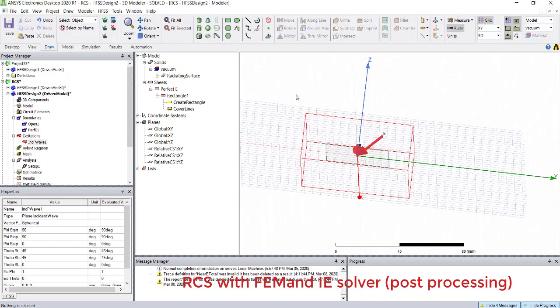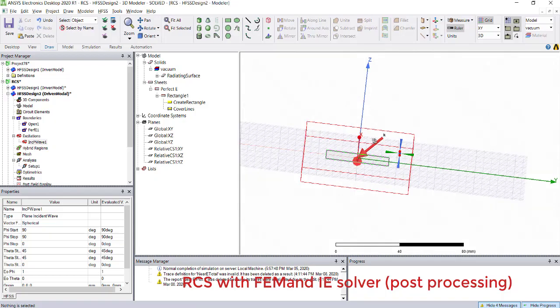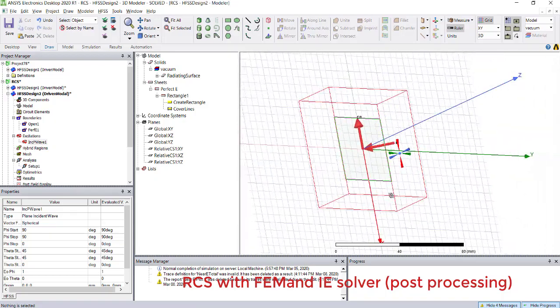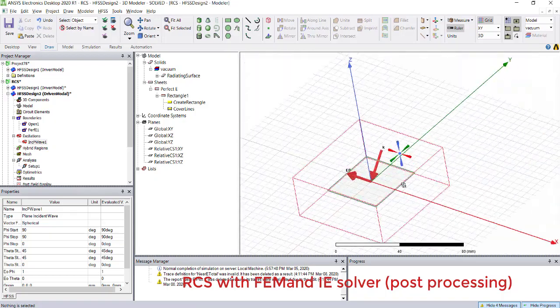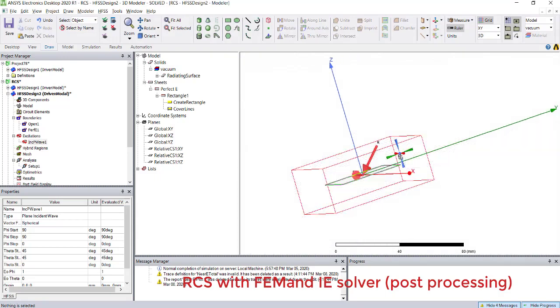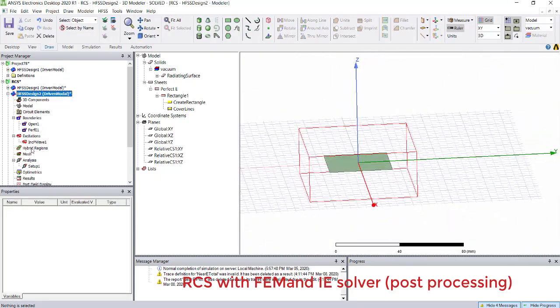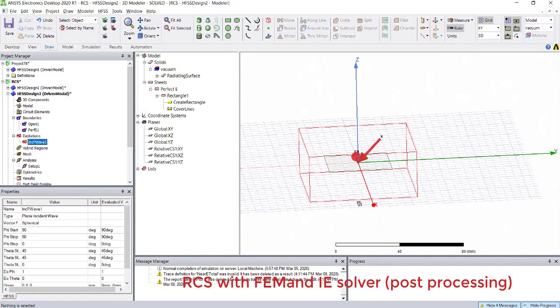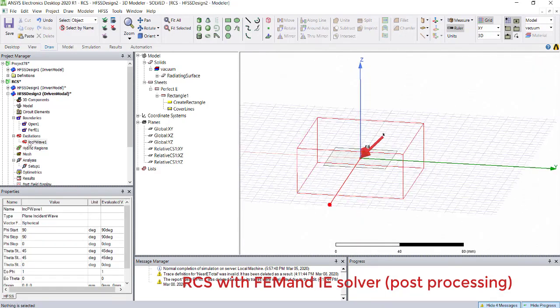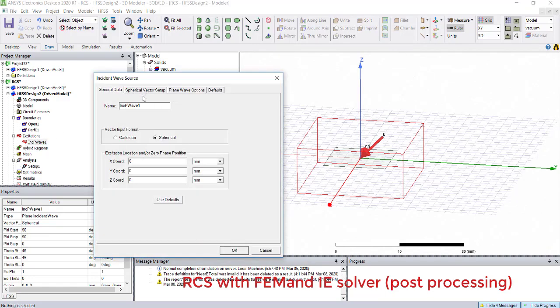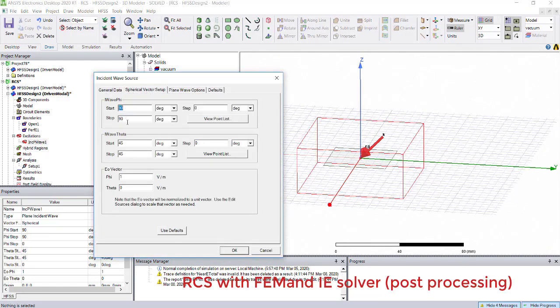and reflecting back. So this is what I wanted to see: how the wave is going to hit, how to see the result, how to interpret data, many other things. So we'll see today how to see the RCS post processing. I hope you can understand from this data which angle this is going to be incident. This is going to be incident from theta 45-degree.